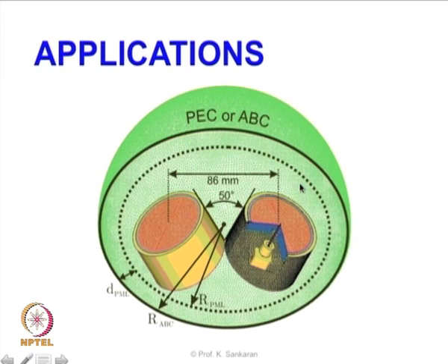And with this, what we are interested in is computing the S21 parameter. One of the antennas is excited with a wideband pulse, with the pulse width we have discussed, and we are interested in the coupling parameter, S21, to the second antenna.